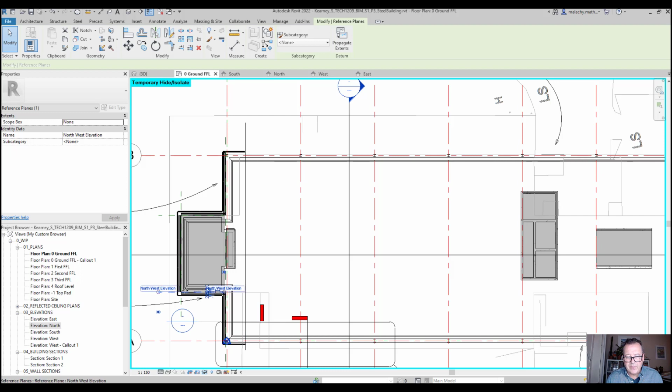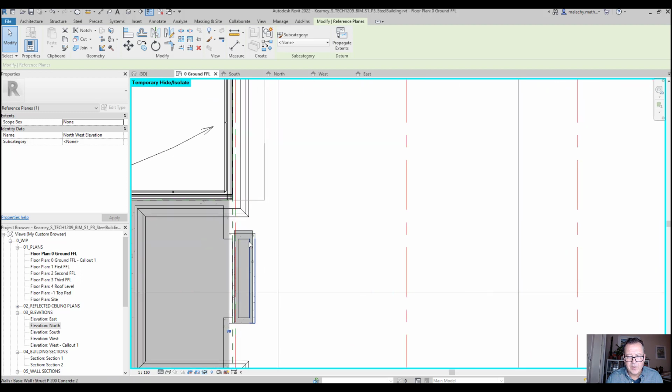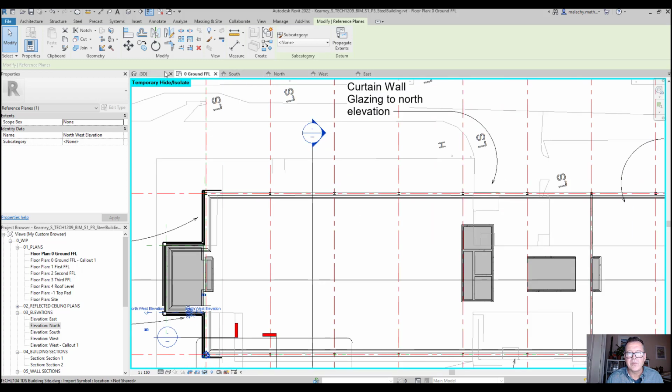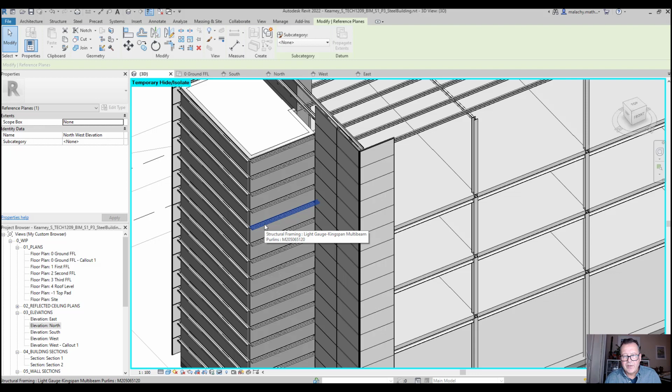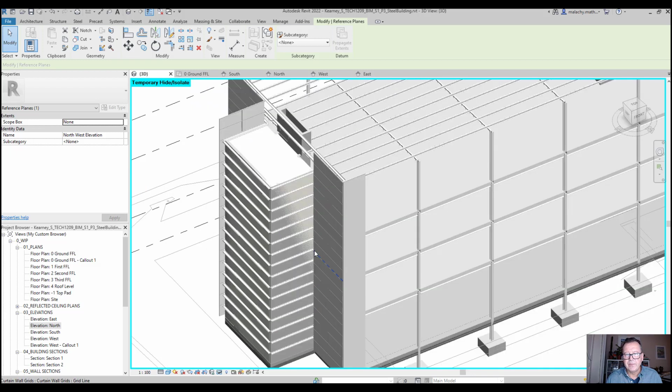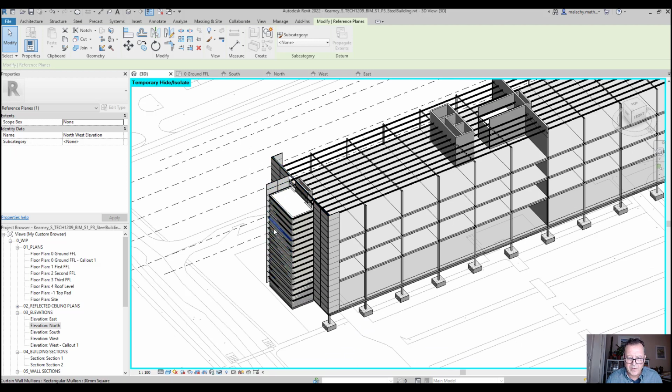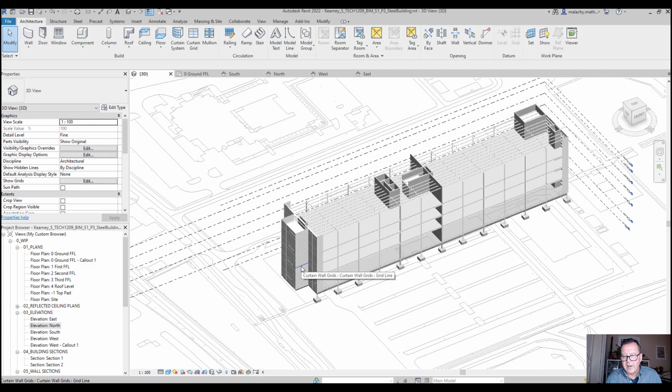I also created some walls in here, the same type of walls as the other core. So I created core walls in around here that I can hang those mullions, those Z purlins off. Okay, and so I created a beam system, beam system, beam system, all the way around, and then I created the wall and took that all the way around as well. So using the exact same techniques, I was able to create that there.